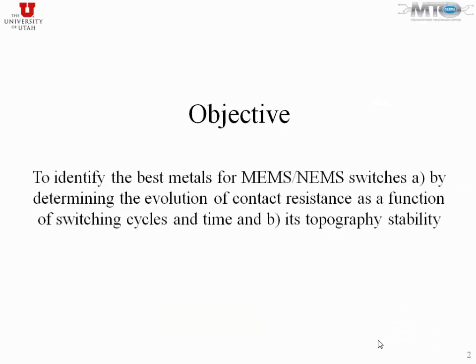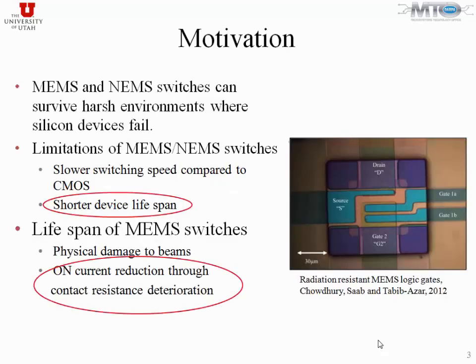So the motivation for this work is to come up with an understanding of different types of metals that you can use for hot contact microelectromechanical switches. And the idea is to not only look at different types of metals, but also understand how different parameters like their density, melting point, stiction force or adhesion force at the surface, Casimir and van der Waals play a role. So we have been working on this problem for a long time, since 2000, 2001, 2002.